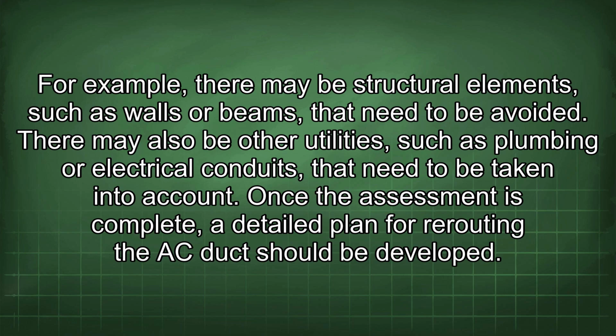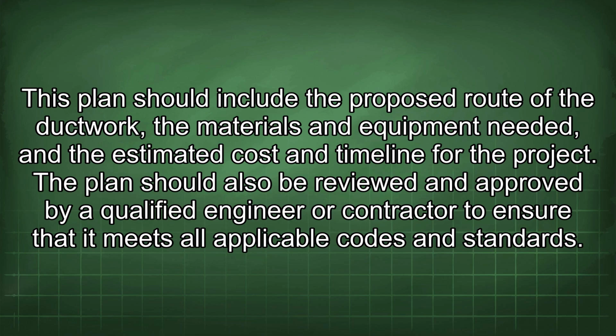Once the assessment is complete, a detailed plan for rerouting the AC duct should be developed. This plan should include the proposed route of the ductwork, the materials and equipment needed, and the estimated cost and timeline for the project. The plan should also be reviewed and approved by a qualified engineer or contractor to ensure that it meets all applicable codes and standards.